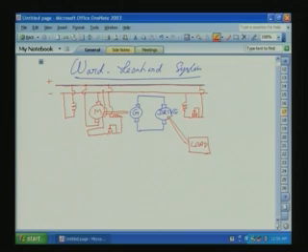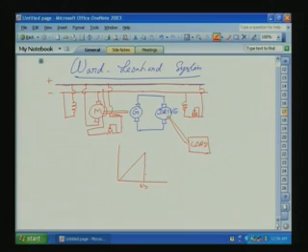So, this machine will be working in the constant torque region, that is this region. Armature voltage is controlled, we can have constant torque depending on the load here. So, slowly we are increasing the armature excitation, that means we are slowly cutting down the resistance. When this resistance is 0, the field excitation of the generator comes to the rated excitation. So, the drive has come to the full speed omega b, our drive motor. That means armature voltage has come to the full.